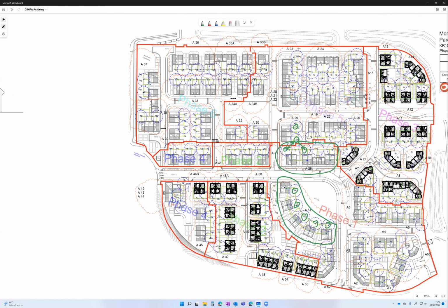Is there a rigorous method for estimating diversity of flow rate in these systems? There isn't a published document on it. We design to our standards that we agree with our heat pump manufacturer customers. And it does vary depending on the manufacturer of the heat pump. So to give you a flavour for what that looks like, particularly with flow rate diversity, it would be over designing a network if you designed for optimum flow rate with 100% of the units running. When you've got 100% of your units running, you would actually design to the minimum flow rate for those heat pumps. So that gives you that leeway to take that diversity in there. So we do it in agreement with the heat pump manufacturers we're working with.